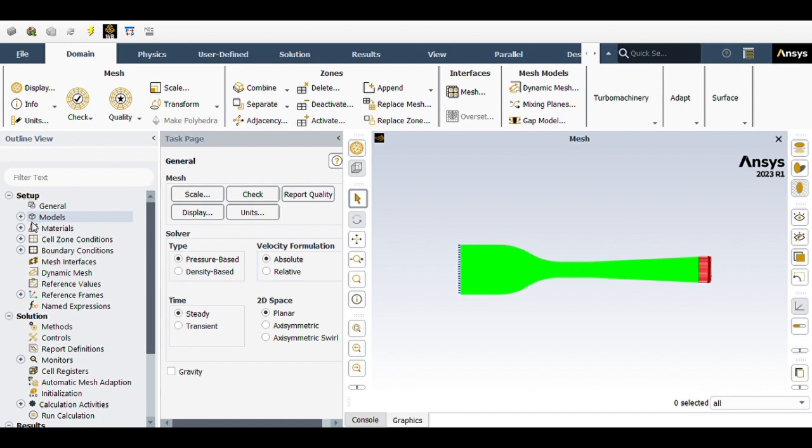For the purpose of this video, we are going to run inviscid flow at a fan frequency of 60 Hz, which corresponds to a test section velocity of 14.5 meters per second, which corresponds for this geometry to approximately 4.5 meters per second entrance velocity.